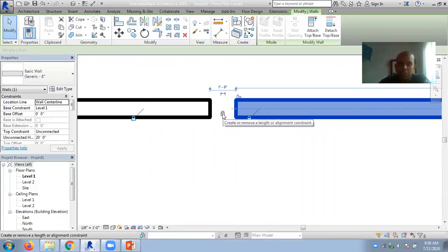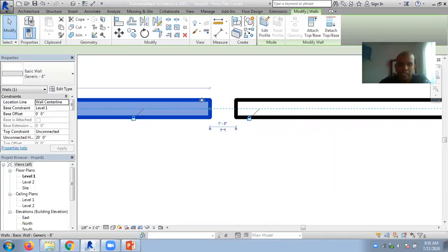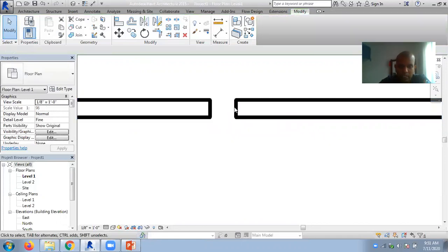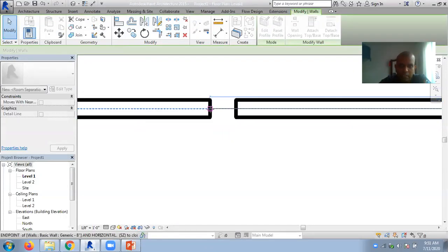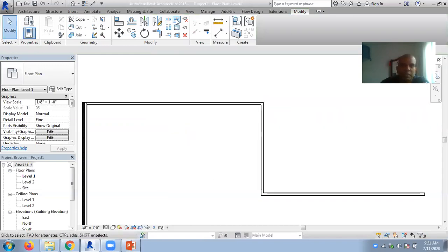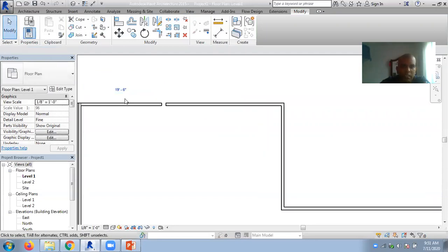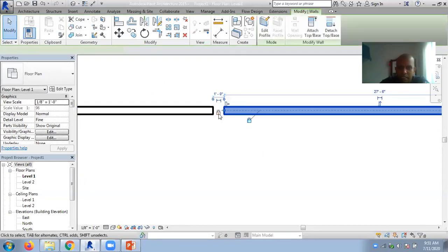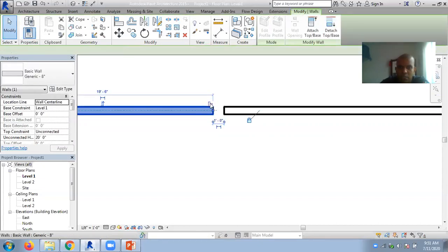This will allow you to move the wall. This will allow you to join this side of the wall, and here also click here. I think this is okay now. Come here. So I redo it quickly. Split with gap. Give a gap, say 1 foot. Now I have a lot of locks here. Unlock it here. Allow join from this side. Allow join from this side.